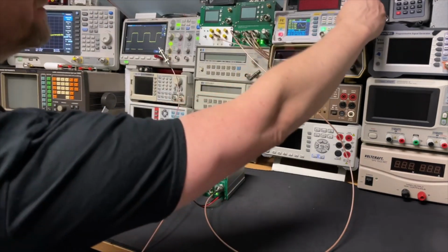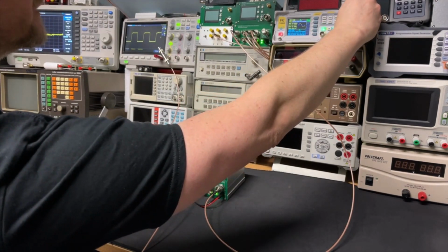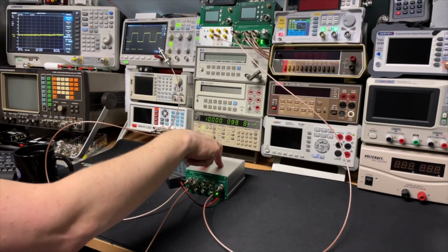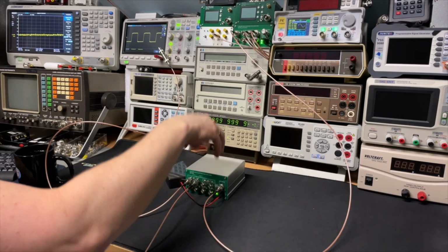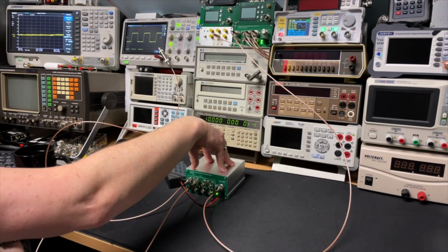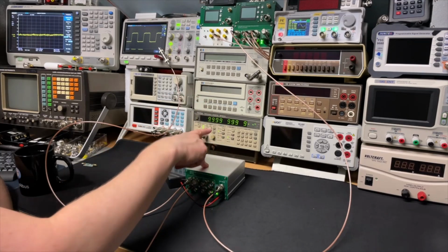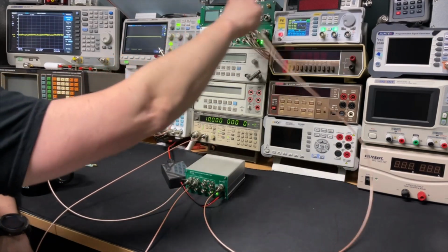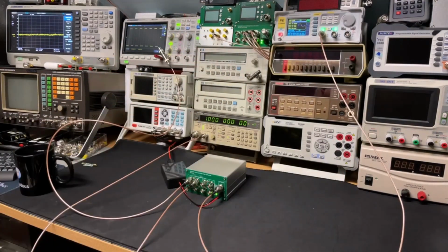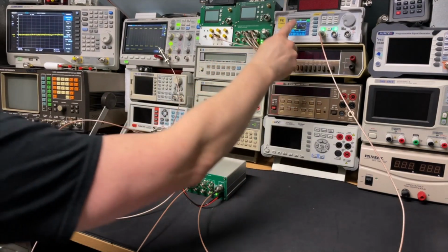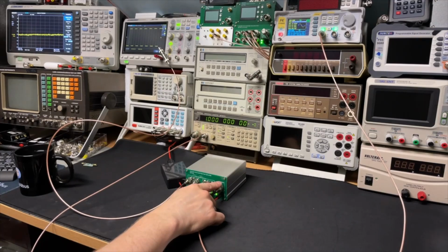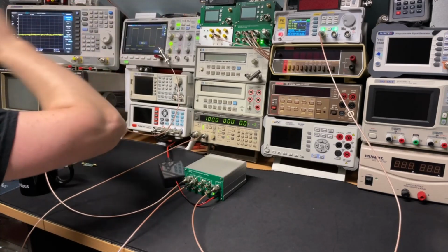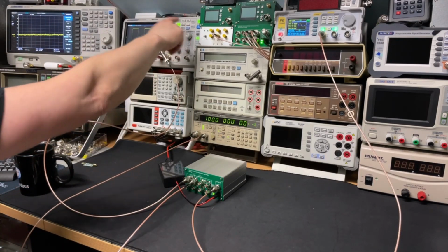What we also can do, let me get the signal generator, because that is the nice thing of this one. This one is not specifically made for 10 megahertz. You can use this one also to distribute from DC all the way up to 200 megahertz. And that is a nice thing. So what if I put 1 megahertz? Well, it will just do that. 1 megahertz here, 1 megahertz here, and then it distributes over all 8, and it's just 1, 1, 1. And let me do another print.